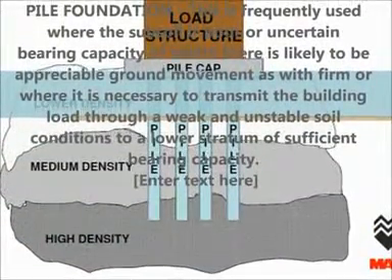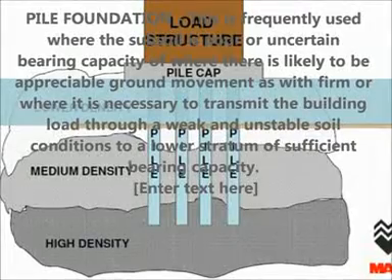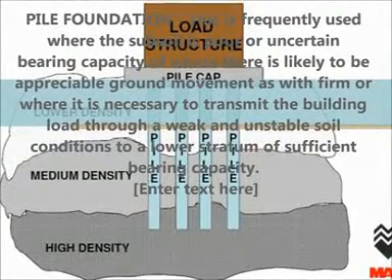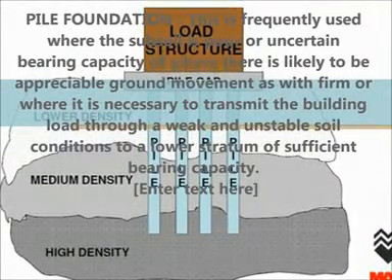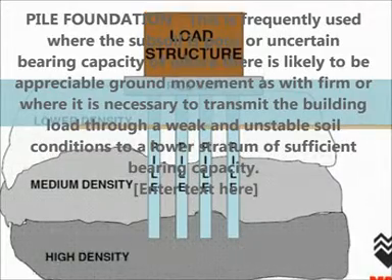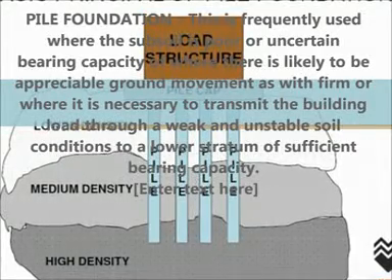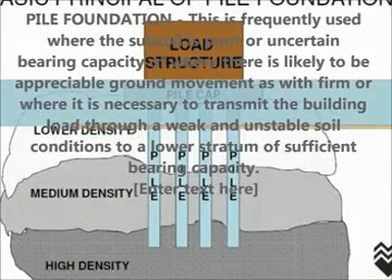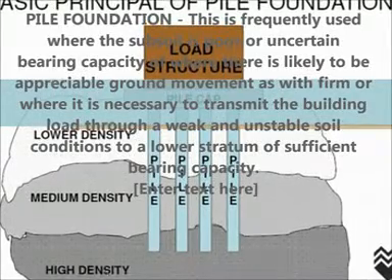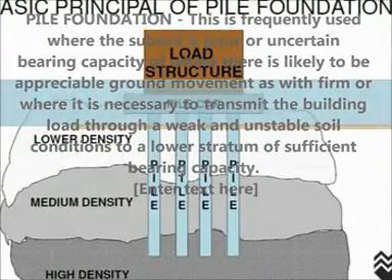This is frequently used where the subsoil is poor or of uncertain bearing capacity, or where there is likely to be appreciable ground movement, as with firm clay, or where it is necessary to transmit the building load through weak and unstable soil conditions to a lower stratum of sufficient bearing capacity.